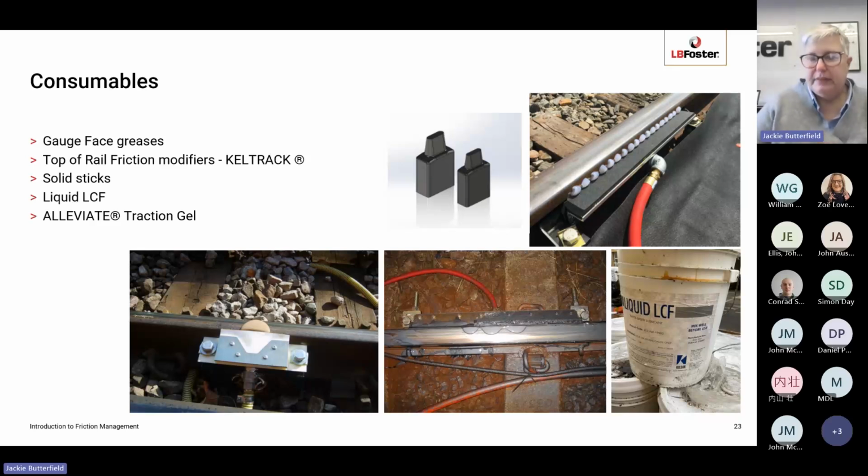So as the wheels come out of the depot and they hit all of those switches and crossings, there is a much greater risk of wheel climb derailment. And so by painting on this liquid LCF after the wheel turning, you're just reducing that risk until the wheels are back to their normal roughness in their normal operating state.